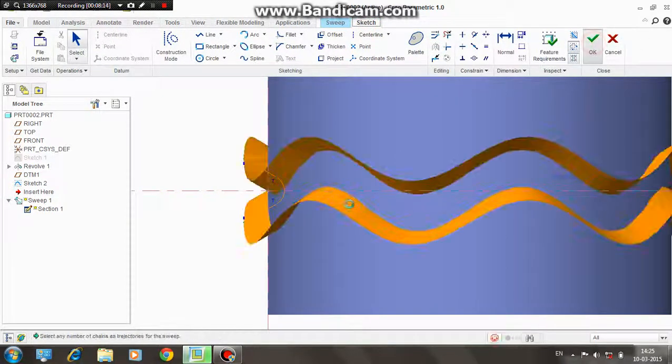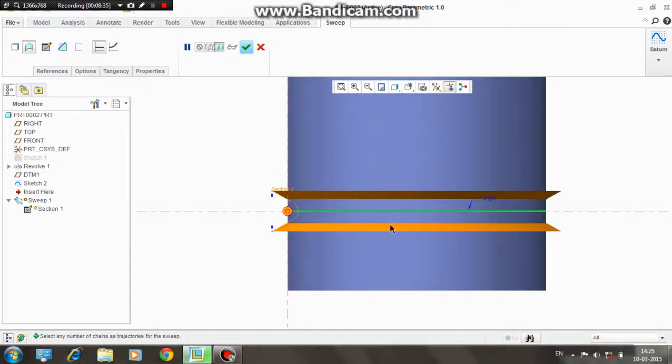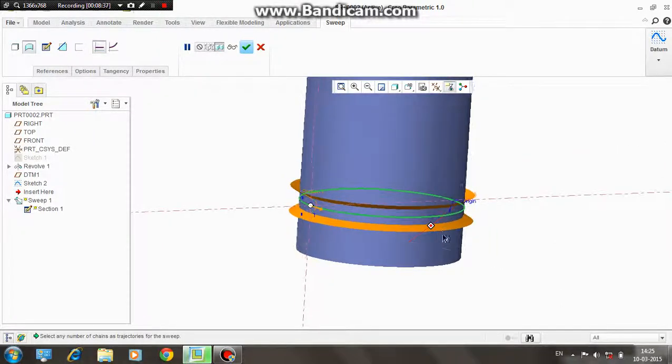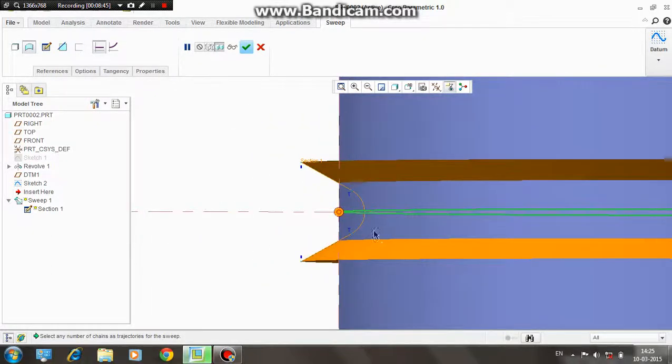Now click sketch. The very important thing here is that I have turned on this parametric references icon. Means for having sketch modeling according to the relation, this must be on. If it is off, you have to turn this on. Otherwise it is simply a cross section floating about this trajectory. There is no relation, I haven't taken the relation we have typed there. Okay, click OK.